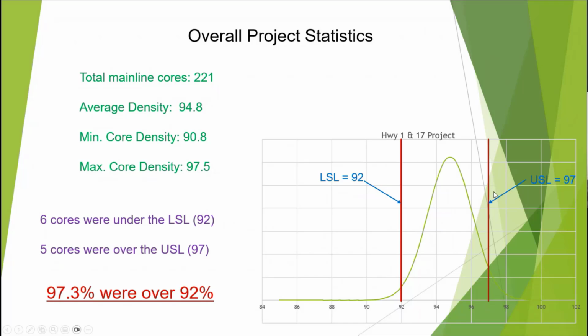The whole purpose of the upper spec limit initially was you didn't want to overroll the mat. Well, my experience is if you overroll that mat, you start crushing aggregate and your density drops like a stone, pardon the pun. And so, you can see that in the field. You can feel that in the field. That'll take care of itself. I'm not so much worried about the upper spec limit. You just don't want the law of unintended consequences of somebody sliding this whole thing back because they're worried about this.